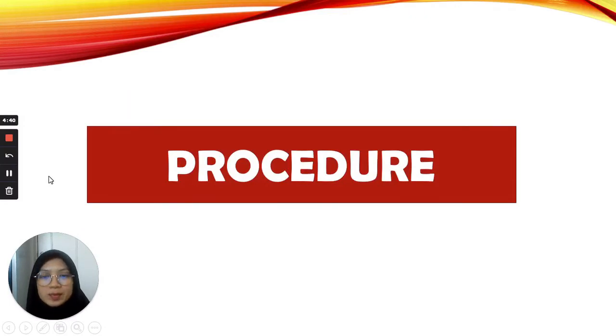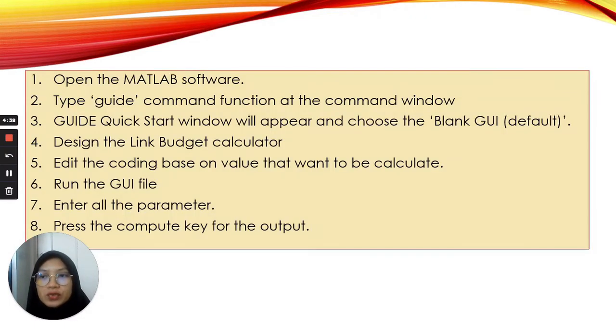Okay, next I will explain the procedure. First of all, we need to open the Matlab software and then type the guide command function at the command window. And the guide quick start window will appear, and we need to choose the blank GUI default.